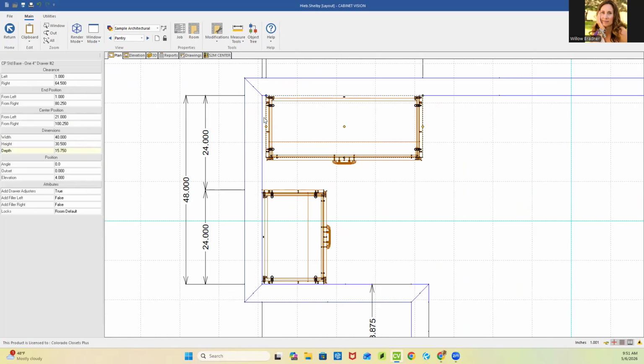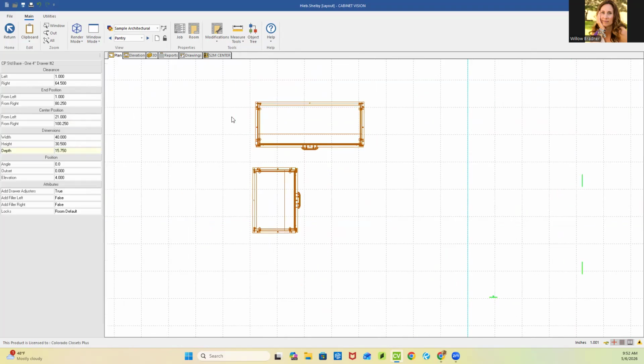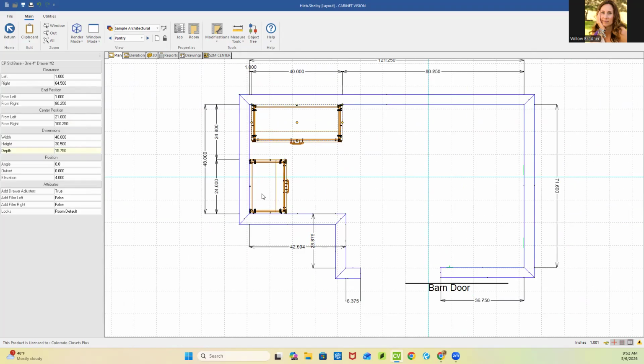First off, I like to leave a couple inches of space here. We're trying not to lose space in the corner when these come together, but I want to leave a couple inches because anytime you have two cabinets meeting in the corner, the junction between those two cabinets is very precise and the walls tend to be less precise. And so if you can leave gaps in strategic locations, it gives flexibility for the installers on game day.